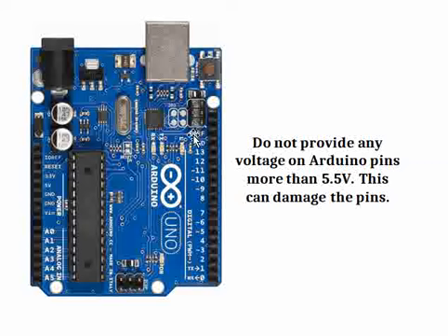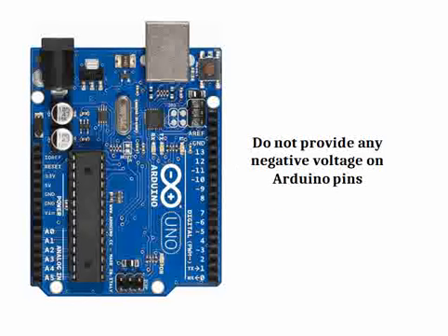So this is a very important point we have to keep in mind, because the first thing that we do is power up the board or connect something to the Arduino pins. So this is a point to remember. And then never give any negative voltage to Arduino boards. Why this is mentioned here is, on the GPIO pins you have diodes internally, and if you give negative voltage, there is every chance that the diode conducts, and it can internally power up other sections. So this is another important point.